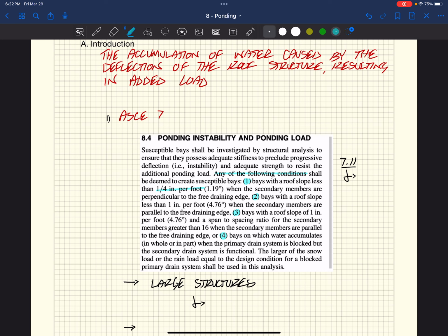Well, usually, I've seen it a lot of times, architects, and you'd have to talk to a plumbing engineer, but a lot of times they have to, by code, provide a primary and secondary draining system. And a lot of times they'll just put them right next to each other and plumb them that way. Other times I have seen them use scuppers and then one of those drains I showed you. And so depending on which system's used, there may or may not be this possibility that if the primary is clogged, there's going to require some amount of water on the roof before it actually gets to the scupper.